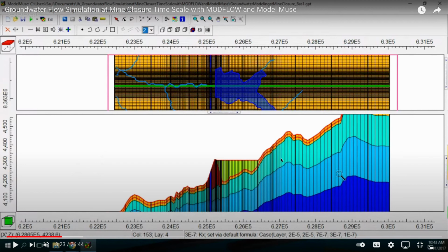If you're an environmental systems engineer, then perhaps you'll be looking at this kind of mine closure problem. And if you're looking at energy engineering, the equations for flow in geothermal reservoirs, for instance, are exactly the same as those in petroleum reservoirs and in groundwater aquifers. So there's a commonality in here that we'll talk about. And really all it comes down to is using conservation of mass. Mass flow rate in equals mass flow rate out, and the difference between those represents an accumulation. And you end up with an expression that is only written in terms of mass, and what you need to account for is this second thing that we've talked about in terms of head losses.